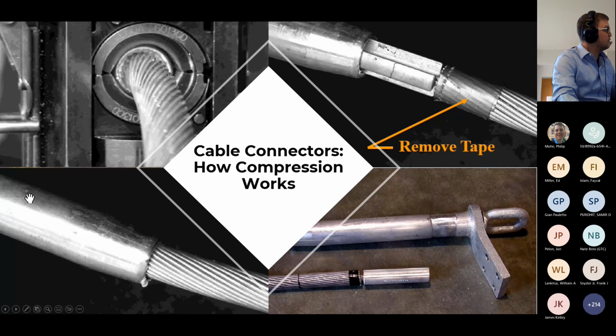And this picture right here is a good example to show you the compression connector. You only have 2 members, the top half and the bottom half, pushing inward to crimp this inside the barrel. Whereas if this was a swage connection, you would see many little teeth, and they're all pushing inward rather than a downward and an upward force. And then this picture I like to use is as you start to crimp it, you'll start to notice the oxide inhibitor starting to seep out. There will be a little hole at the end of the barrel here where you actually take your oxide inhibitor to fill it once you put your cable inside.